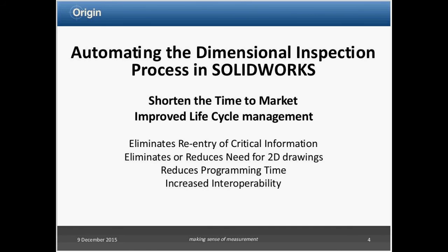In the case of making those final inspection reports, we're looking from the program, from the soft gauge out. Things that are outside the range, we don't care if there are points out there. Those outliers out in space don't matter; they're not being considered anyway. So yes, we have filters, and on the other hand, they're not as required because of the technology we're using to create those reports.